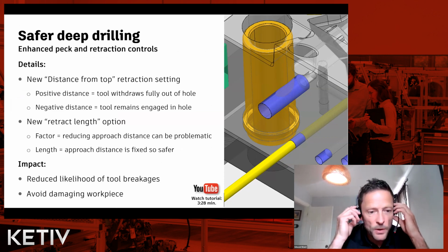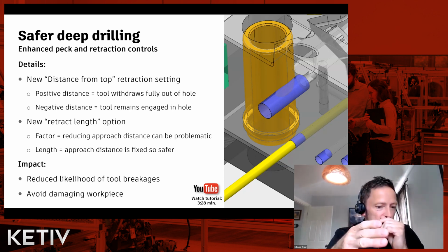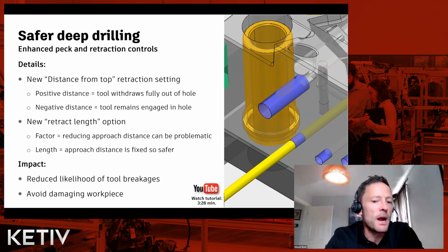Now, anyone that's done this kind of work with deep drills knows that they are not always running true, they're wobbly, basically. So in the machine, they could be running out, not a problem once they're in the hole, but the initial engagement of the hole could be an issue where the tool could catch on some swarf, or the long and short of it is it could end up damaging your job.